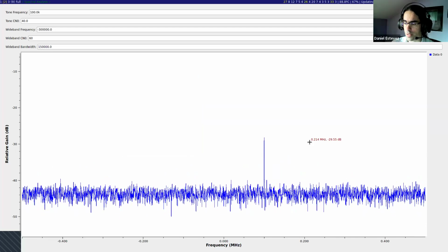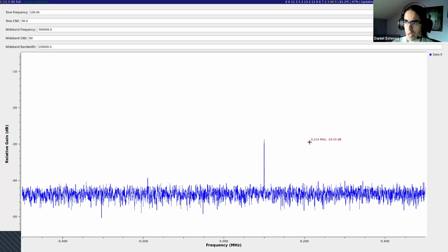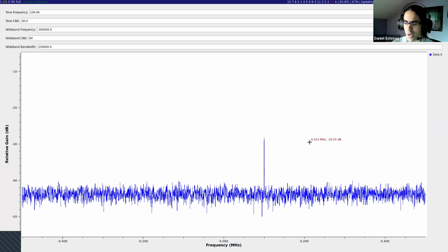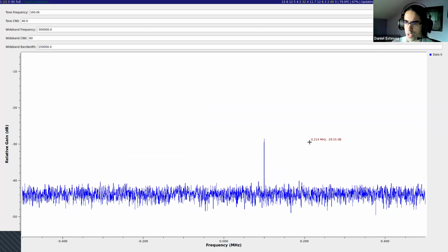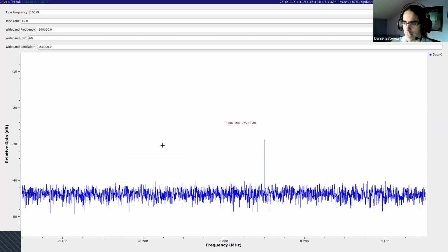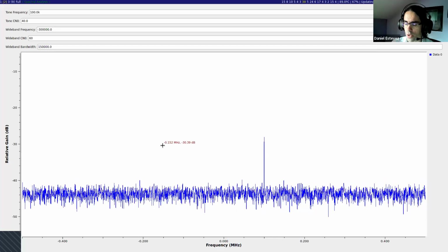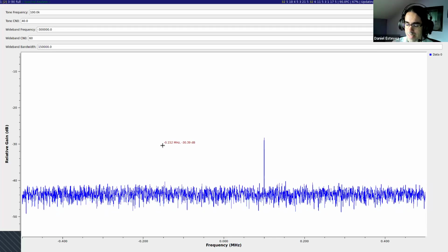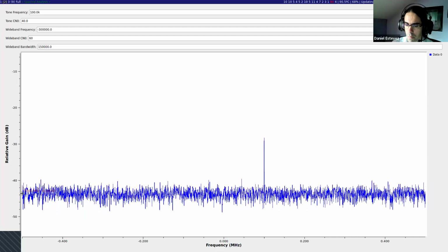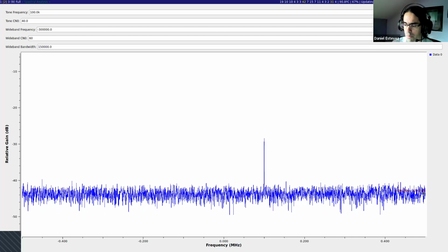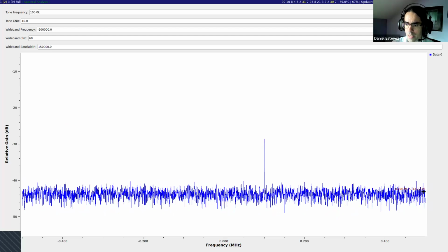and it is 1 hertz. And why 1 hertz? Well, because hertz is the unit of frequency, and 1 is the most simple number you can have. It is a tiny bandwidth to measure noise. So usually the way this is done is you measure noise in practice in a larger bandwidth. So you might measure the noise in all your 1 megahertz bandwidth if you need to measure experimentally.